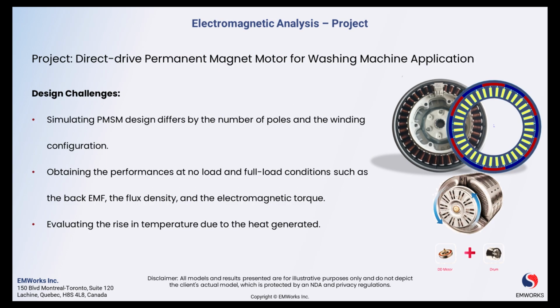Moving on to application examples, let's look at an electromagnetic simulation project for a permanent magnet synchronous motor design. Some key challenges include modeling different pole and winding configurations, calculating torque production and back EMF waveform, and evaluating temperature distributions under load.